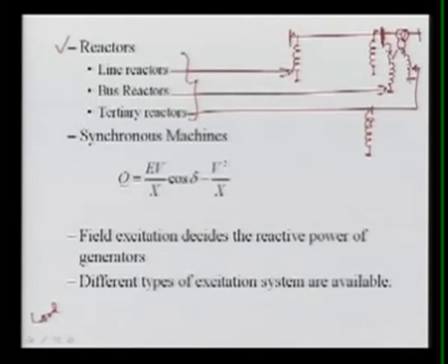But here what we can do is, with the tertiary winding, normally let's suppose we are using a 400 by 220 kV transformer, and it is having a tertiary winding of 33 kV. So the insulation level of this reactor is very, very less, and then it can provide this reactive power absorption whenever required. At the same time, this tertiary winding can absorb the triple-N harmonics current, which can circulate here. So this is your tertiary winding.